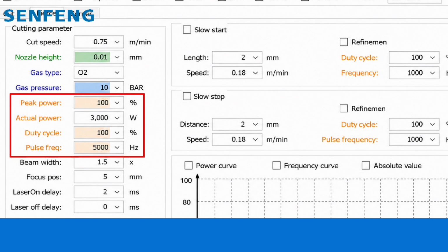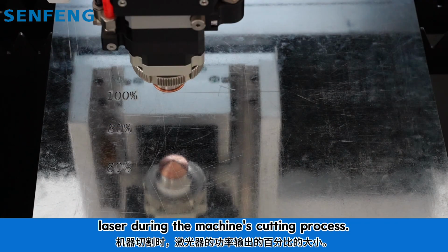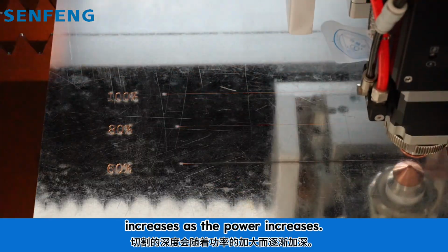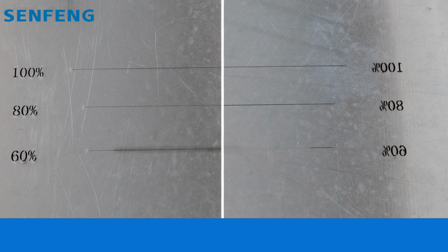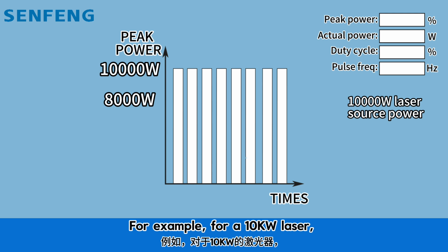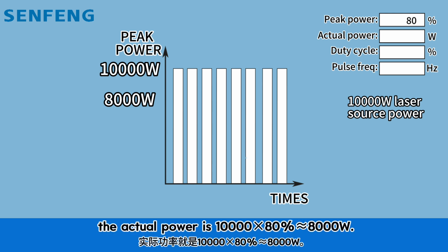Peak power. The percentage of the power output of the laser during the machine's cutting process. The cutting depth gradually increases as the power increases. Actual power equals peak power times laser power. For example, for a 10 kilowatt laser, if the peak power is set at 80%, the actual power is 10 kilowatts times 80%, approximately 8,000 watts.